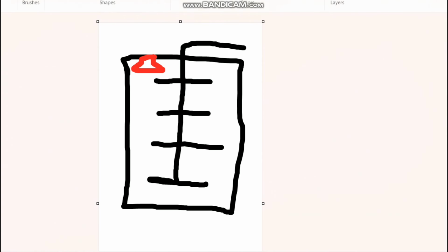So we have the arrangement like this. As I have shown you, we have the package unit located here. From the unit we have the supply duct, which is properly arranged with square diffusers at each branch, and with proper volume control dampers. Coming to the return, we have only one common return air plenum for the full conference room. So the issue is we are getting some indoor air quality issue and comfort problem.